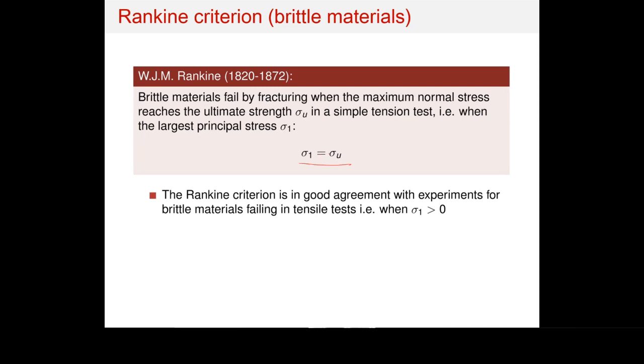At least, I mean, you usually need to apply some safety factors in there. So you reduce the sigma ultimate. You don't take exactly the same sigma ultimate you get from the experiment. And you also assume that this is going to be the maximum load you have. So you try to calculate the maximum possible loading scenarios you are going to have, and you pick the most critical one, and you take the most critical point, and at the most critical point, you calculate the principal stresses, and you take sigma 1, and you compare it to sigma.